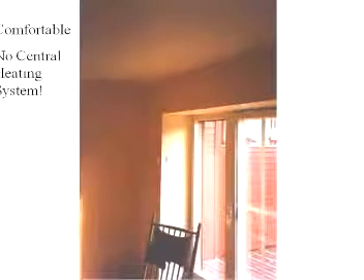Why? Because in fact these walls are about a foot thick, and they're filled with insulation. The windows are also triple glazed so that you get very high efficiency. In this case, they found that in most situations, the amount of energy given off by the residents of the building, as well as by the energy efficient appliances, is enough to keep the buildings warm.